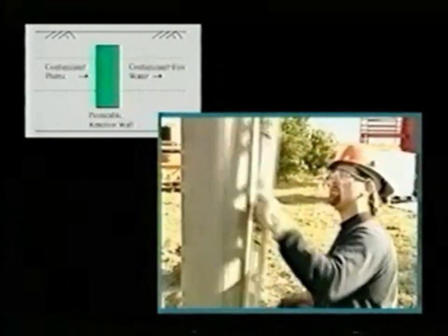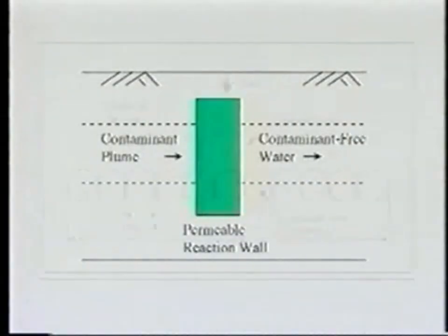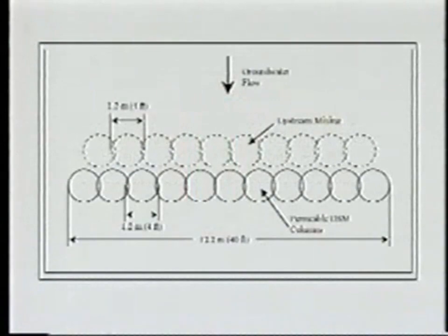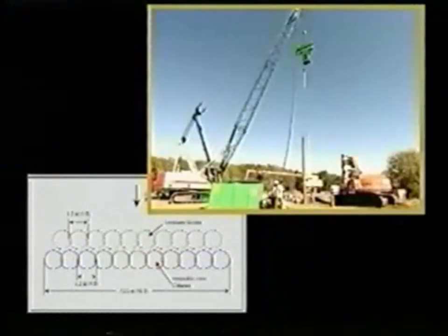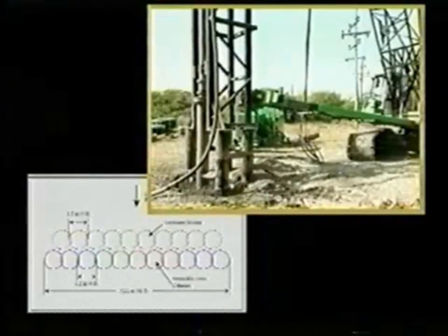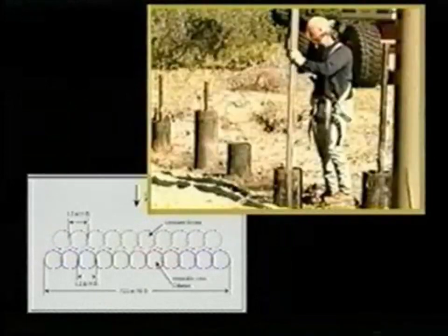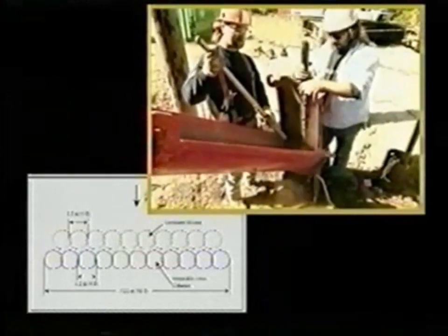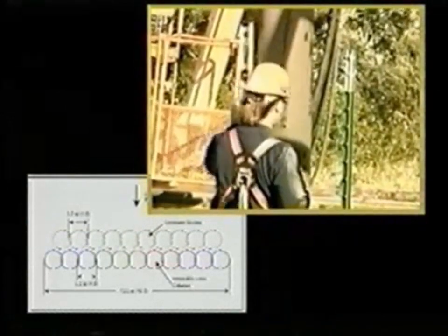However, the combined technique allows for installation of considerably greater depth. The design for this project included 11 deep soil columns with 10 upgradient boreholes to ensure perpendicular flow through the treatment zone. It consists of deep soil mixing columns combined with a mixture of iron and gravel, which are installed into the subsurface soil using vibrational techniques.